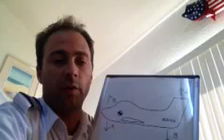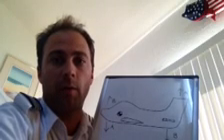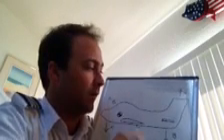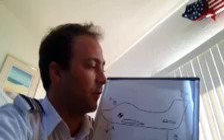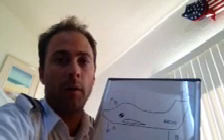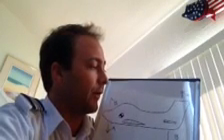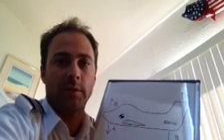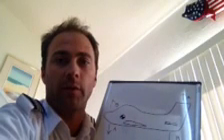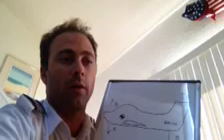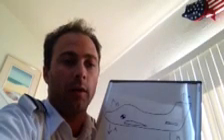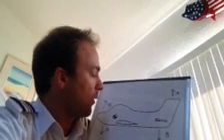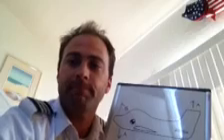And you actually adjust those on the ground, and they have the same operational characteristics as the ones that are changeable by the pilot. They are one-time use kind of things. You try it, you go up and fly. That either was or wasn't enough. Come back and do it again. So they're not very accurate. They're not adjustable during flight, and that's about all we have for our trim tabs.